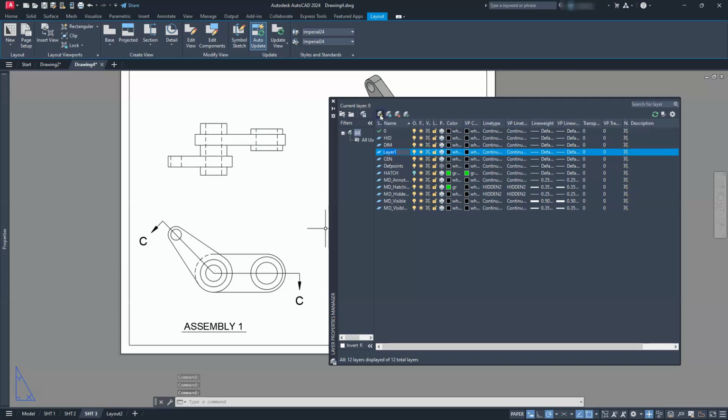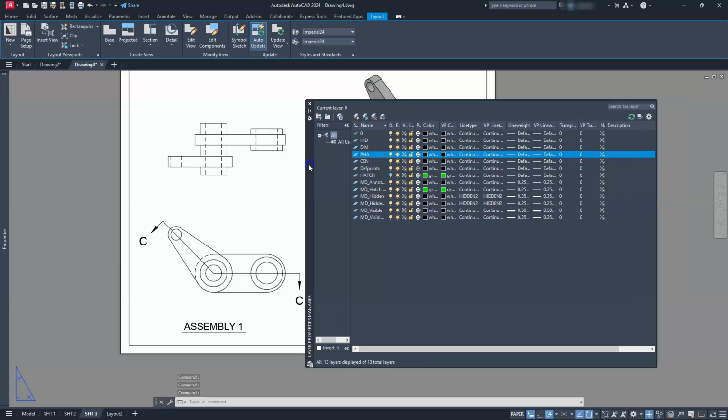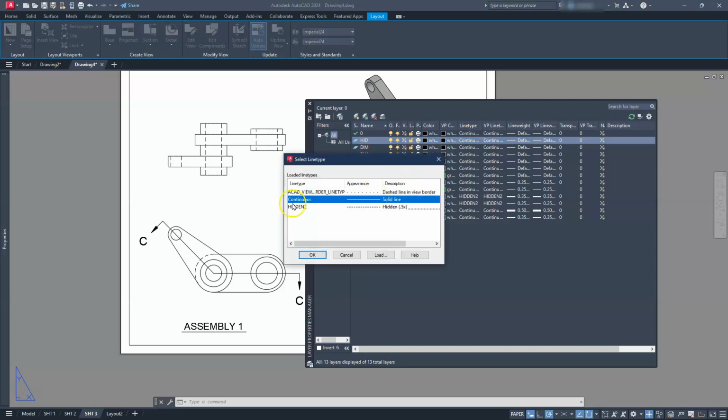And then finally I'll create a phantom layer, right? So PHA. All right, and I hope you can see these, and I'll try to remember to zoom in on this as I'm creating this. Okay, so with the hatch here, or with the hidden one, let's go ahead and make sure that the line type on this one is hidden.